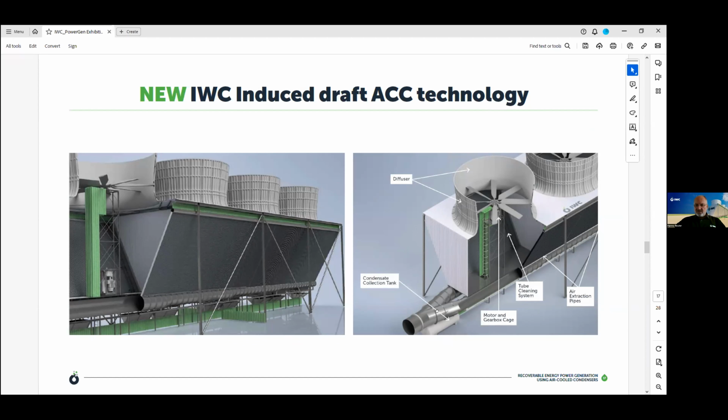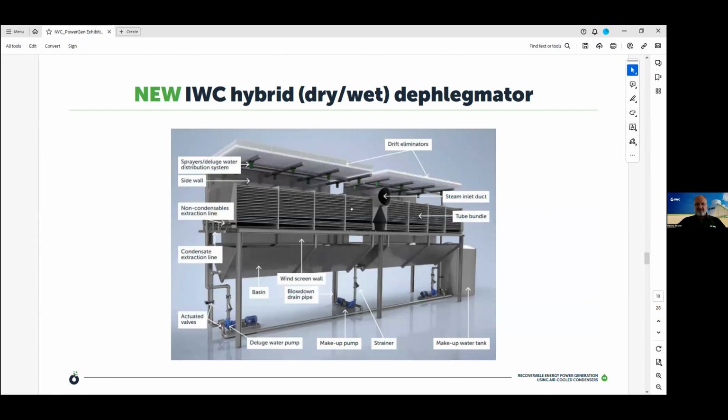So what we've done as well is we've split the steam header here at the bottom in order to be able to fit a hybrid deflector or evaporative cooling booster unit between the ducts. There's some numbers that I'll give just now. So this is in between the steam duct. What it looks like is as I show here, it's effectively a heat exchanger with a bare tube bundle, a bare tube heat exchanger. You see over here.